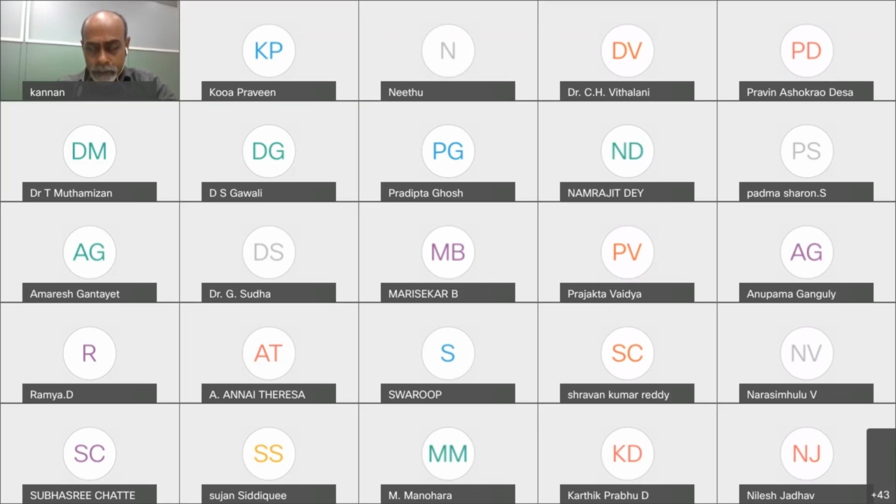Once you find the correct angle, you can then input that value to your software, and this is how the software is written. Please remember that this tool can help you to write the software correctly. You can apply this solver repeatedly, and for different currents, you can get different angles, and you can make what is called a lookup table and put that lookup table in the controller software.